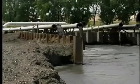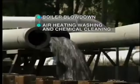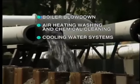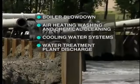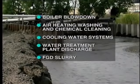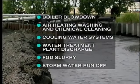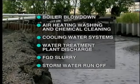The sources of effluent contaminants are boiler blowdown, air heater washing and chemical cleaning, cooling water systems, water treatment plant discharge, FGD slurry, that is waste effluent from a flue gas desulfurization installation, and stormwater runoff from coal piles, ash ponds, oil tanks, and other possibly contaminated areas.